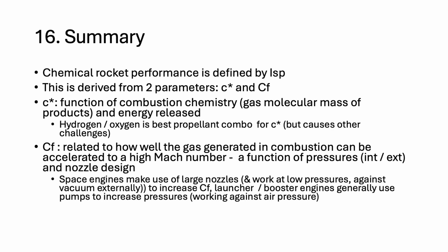CF is really related to how well the gas generated in combustion can be accelerated to a high Mach number. It's really a function of the pressures inside and outside the engine. So you have control over the inside pressures, but not so much over the outside pressures. And that can make life really hard for the nozzle designer. But basically, space engines make use of large nozzles and work at low pressures against an external vacuum to increase the CF. Launcher or booster engines generally use pumps to give them high internal pressure working against external air pressure.